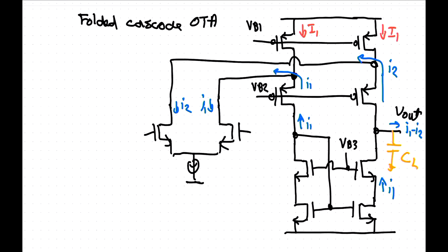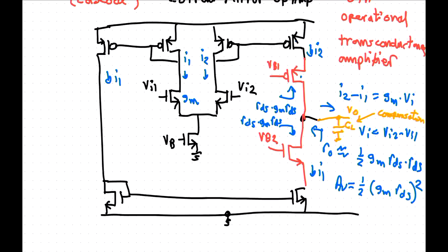Now, if you put most of the current in a differential pair, that would mean that you're scaling this current mirror down. Maybe you have 80% of the current here, then it's only 10% of the current over here. So that's got to be a 5-to-1 current mirror or something like that. And now what we do is we reduce the gain because we're scaling down the current. So you don't do that in this op amp.